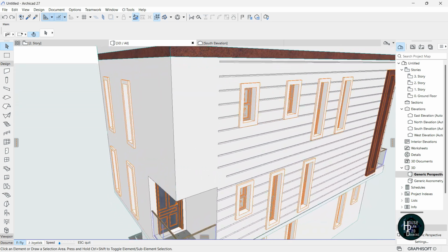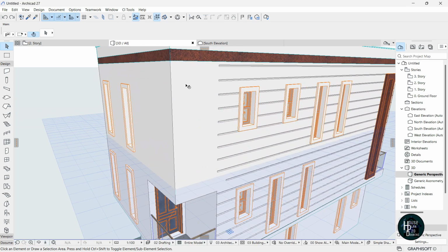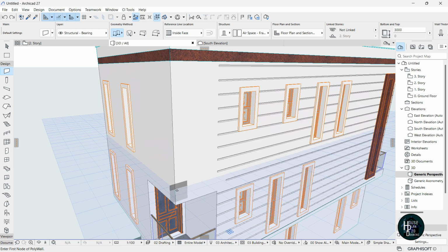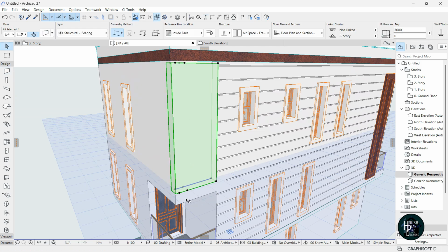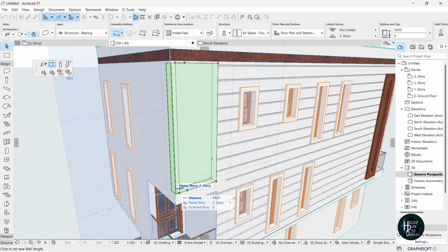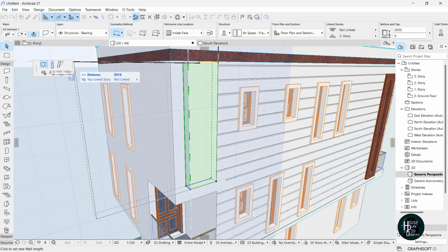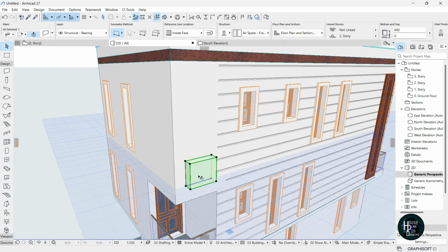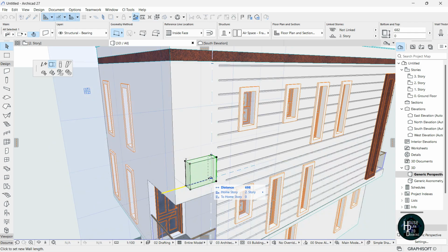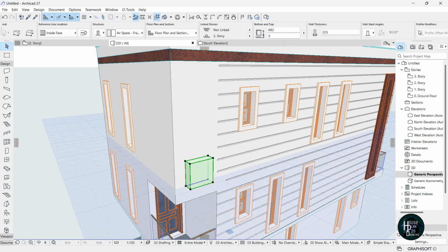Okay, I told you guys I used the wall tool, so I'm going to hold on Alt, select on this wall, just click, drag and double click. Okay, click this again. I'm going to try and click on that node and try and reduce this. Click this, and I'm also going to try and reduce the height. Okay, click this, also try and reduce the height like so. And I'm also going to come here and change this to maybe 50 or 75.